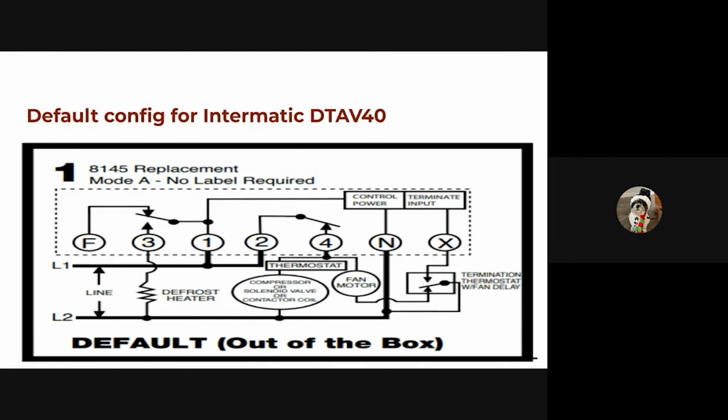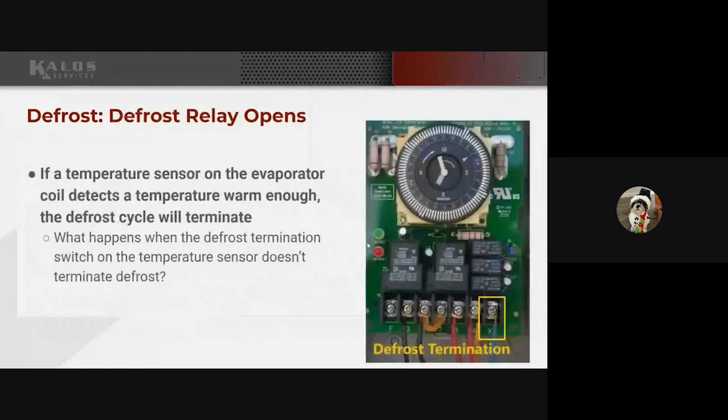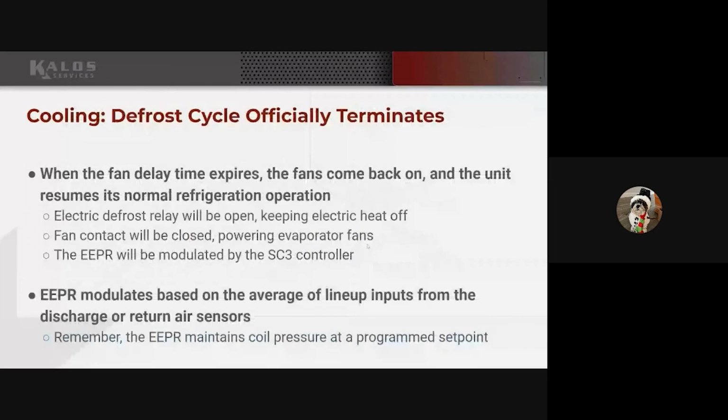So it's about getting used to that troubleshooting and reasoning out, okay, what's in the circuit, and what is the sequence that it's going to run in. If defrost is on, then these other things should not be happening. And if they're both happening at the same time, then there's something we need to diagnose and figure out in the circuit to get it running correctly. That's about all I have to offer on this, which may not be much.